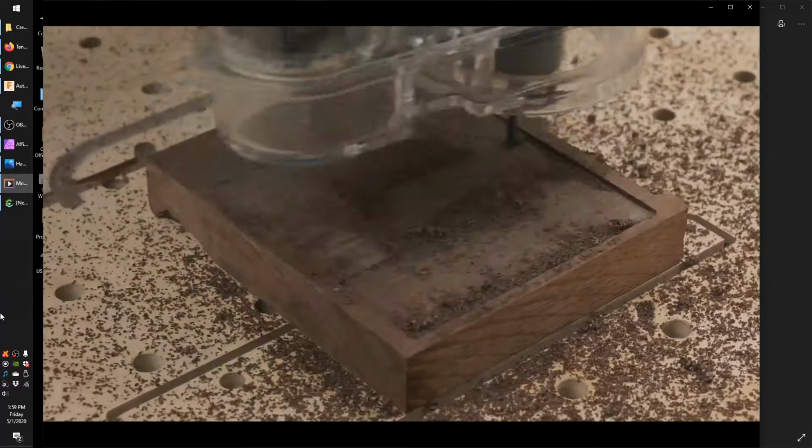So you can see it's defining the islands more and more. But then as it gets to the ocean floor, there's a lot more little features and mini volcanoes underneath the ocean, so it takes longer to machine everything out this way. But eventually, it'll clear everything out, and then we will switch to a parallel finishing toolpath with a 1/16 inch ball nose end mill.